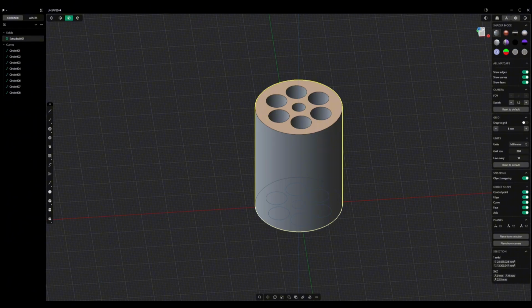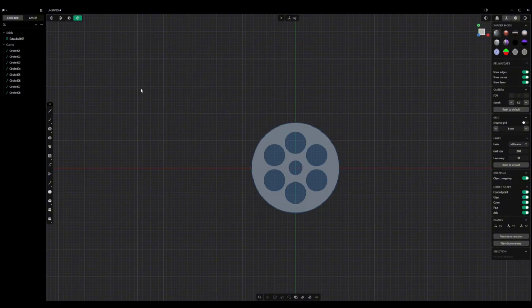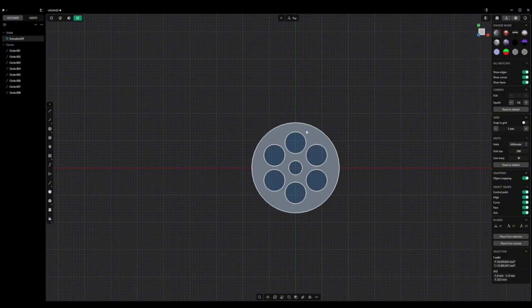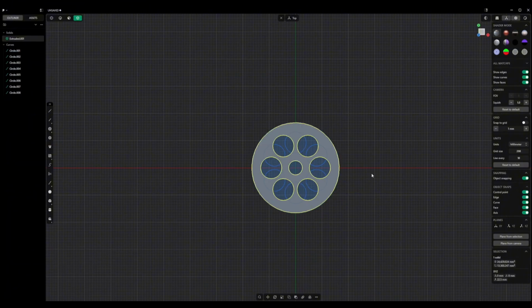So now what we're going to do is we're going to click on the top on the Z axis here. And what we'll do is we will select this object. So make sure you have sheet and solid selected. So press 4, click on it, and then you're going to press R to rotate. And you want to make sure that you're holding down control, so that way it's snapping. And you want to snap to -30. And then you're good there.